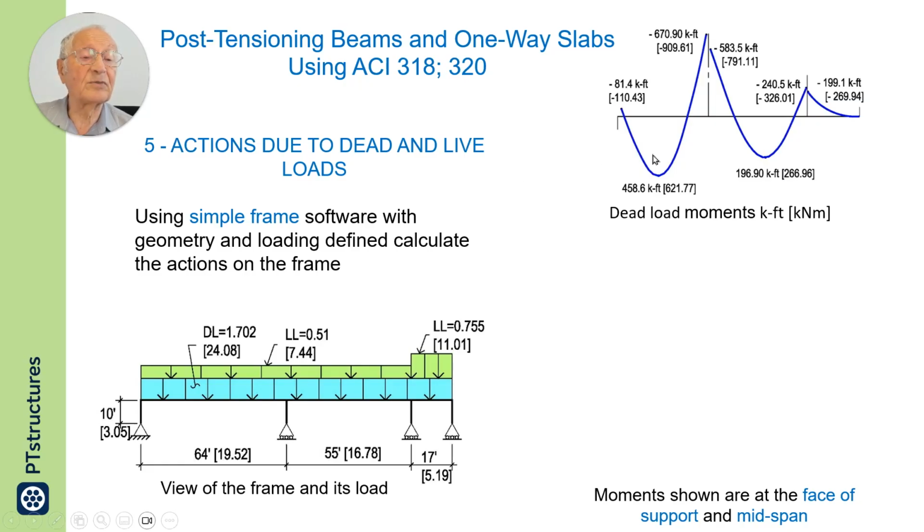Calculate the dead load moment. Select the value of the moment at the face of the support, mid-span, face of the support. Again, face of support, mid-span, face of the support.